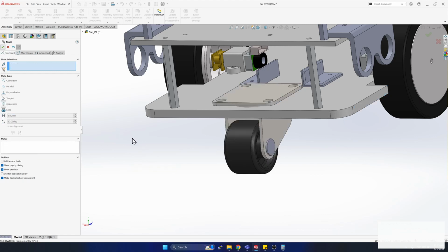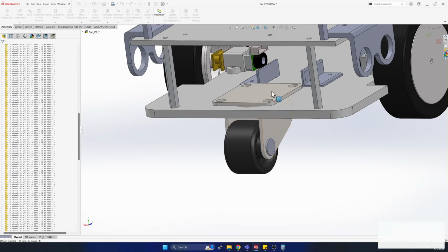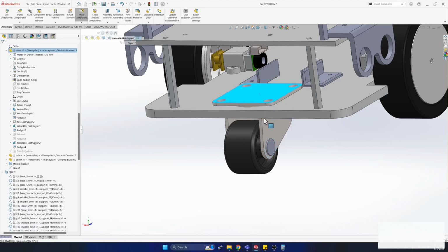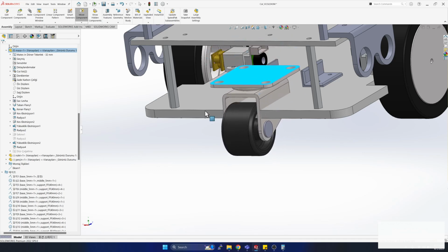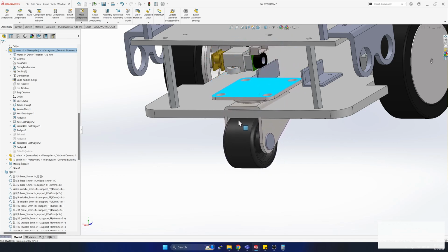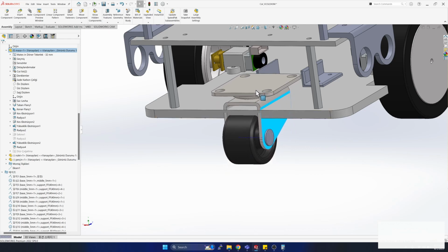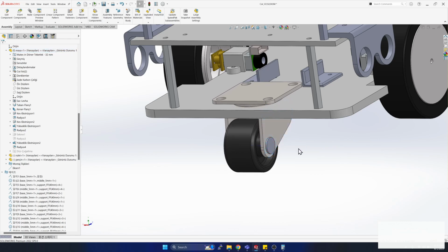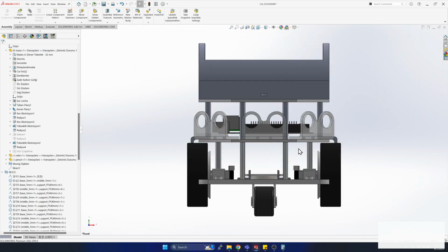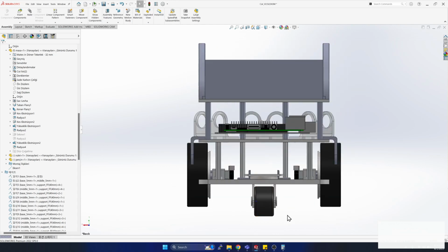The only thing remaining then is basically this z-axis movement, which again it's not doing. Come on, yeah, okay, so it is doing that. Because there are 5 mates, and one mechanical body has 6 degrees of freedom, if you constrain it in 5 directions, then there is only this one direction that it is moving. If I look at it, you can see that it is almost in the center. We'll also use the measure tool to check it.